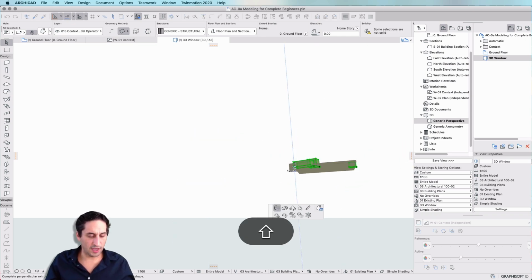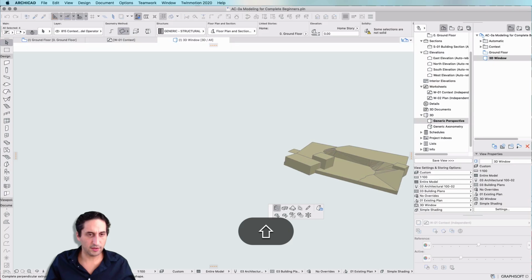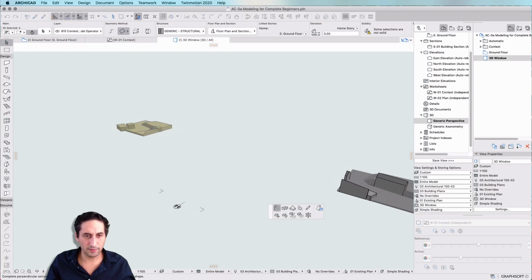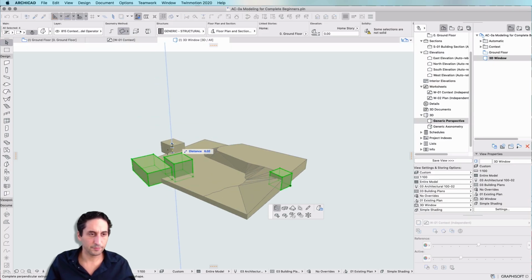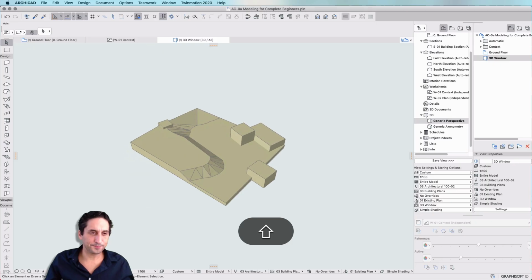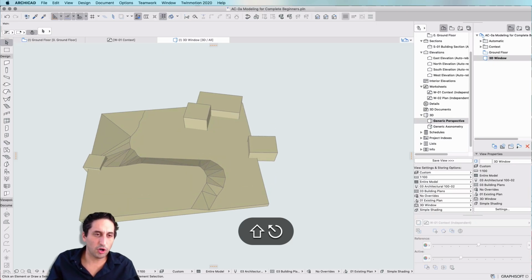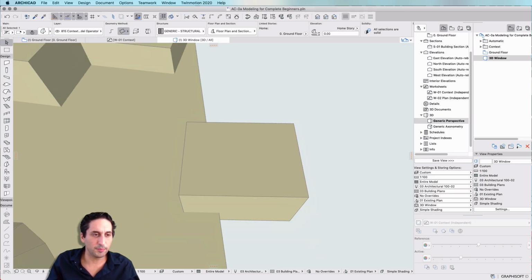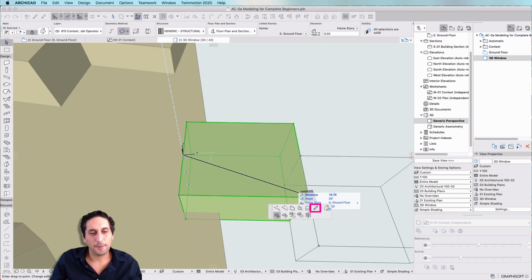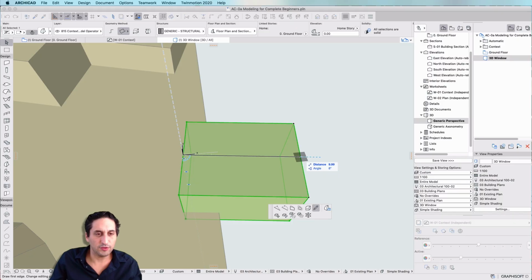If you're not sure about the heights, you can of course always check the one that we already did on the right side. Once you have the boxes, we recommend to draw on top of them from middle point to middle point like this. Long click, pet palette, move on to add polyline, then draw a straight line to the other midpoint and change the geometry method to double click.